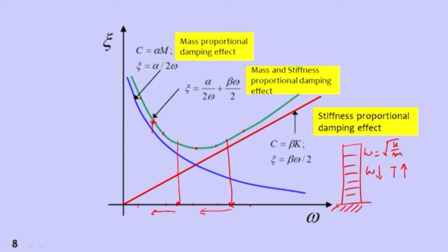That means where we are on this curve, we need to be very careful in applying damping, because zeta has the effect of reducing vibration amplitudes. If we calculate the maximum amplitude in a wrong manner, that leads to either over evaluation or under evaluation of the structure's response.